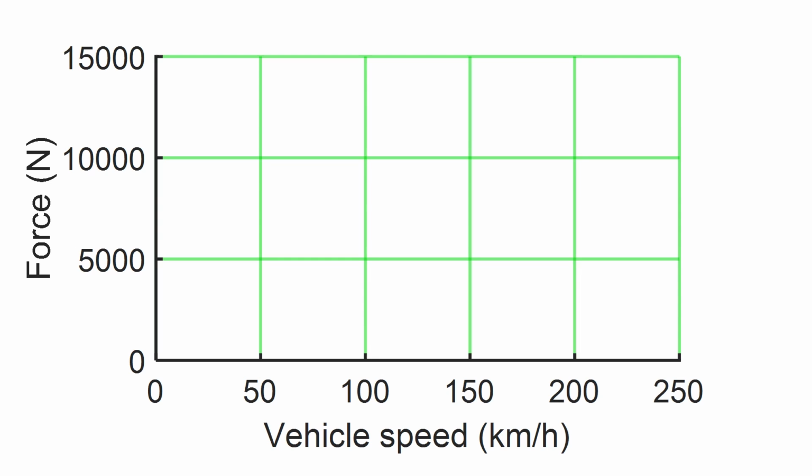Now we can use the vehicle model to calculate what operating points the requirements lead to, and then plot them in a force-speed diagram. We are not interested in each and every operating point, but rather the ones leading to the highest force at each speed. The maximum speed is the limit above which the powertrain does not need to generate any force.